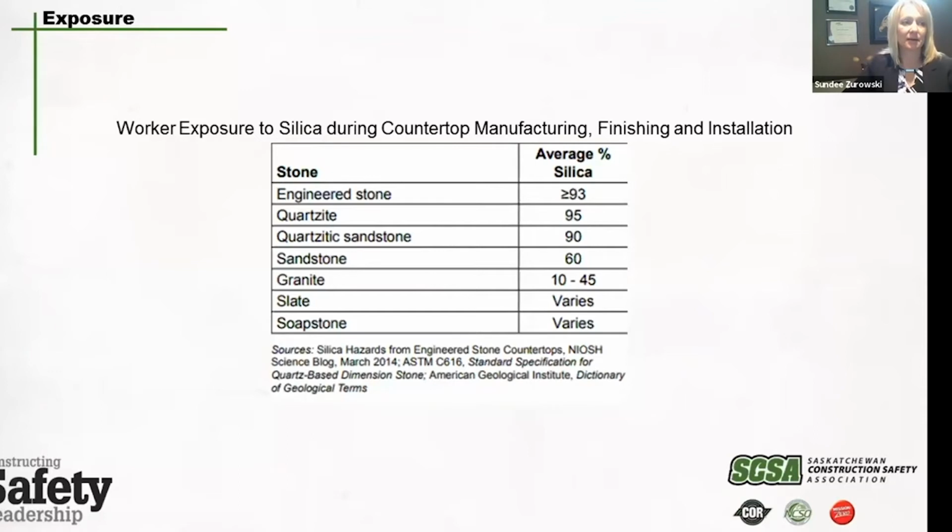The table shown here is from the American Geological Institute. It describes the typical silica quartz content of common natural and engineered stone. Compared to the other stone surfaces, quartz is set apart in that it is not wholly natural. Quartz slabs are manufactured using 95% crushed quartz stone and 5% compound resins. The synthetic component makes it the easiest stone surface to maintain and increases color variety, durability, and stain resistance.